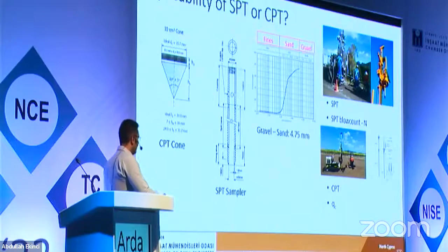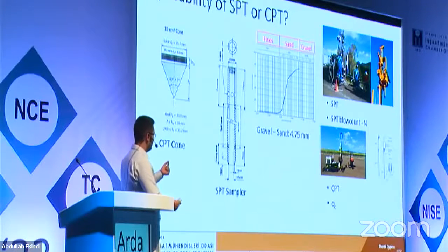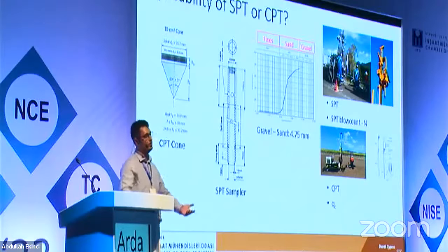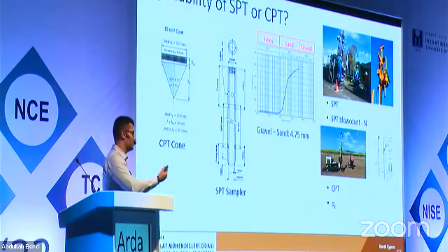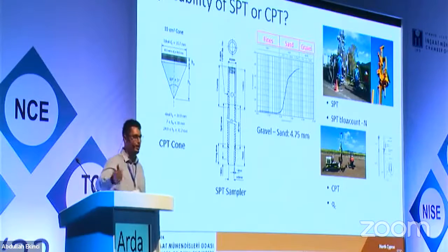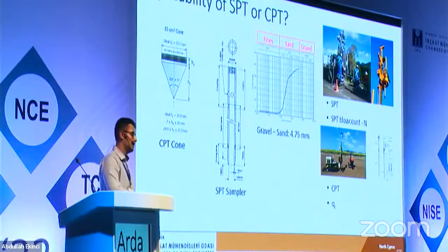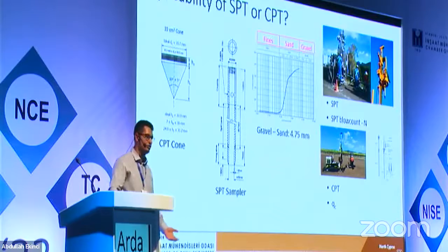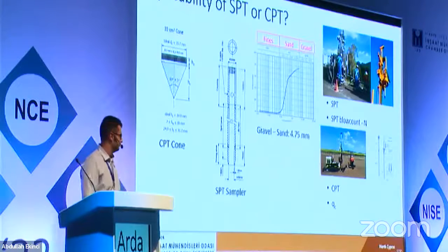What does that mean? The thickness of the SPT sampler and the area of the cone might be measuring the strength of that one particle, not the whole soil layer, which might result in very high resistance. However, it might have very low resistance in the whole layer.